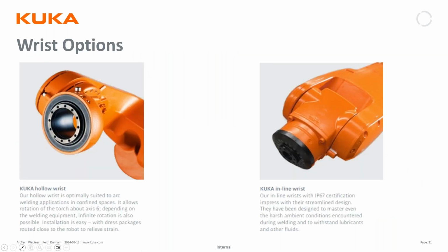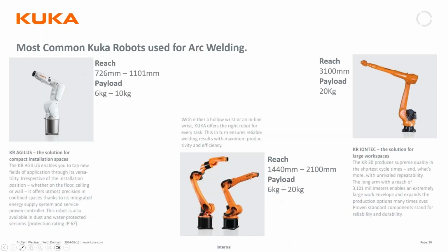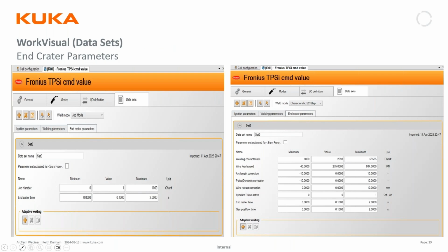I'm going to interject once more real quick. We had a question about I/O, and I'm asking these questions while we're near it, just so we can talk about it. If somebody else has something, we can elaborate. So the question was, can we program all these values to variables and control them from the SmartPad, or what signals do we have access to map to I/O? So ultimately, all these values are already variables inside our system. You could pull them. You can do what you want with them. That is kind of the benefit of KUKA, that it's open architecture. What we do is we build these inline forms to try to make it simple for normal level users. If you're doing a high level application like some of our customers, you can certainly dive way into it.